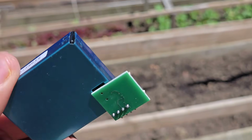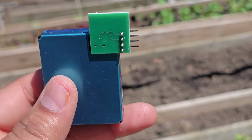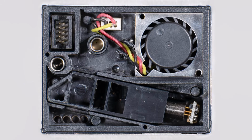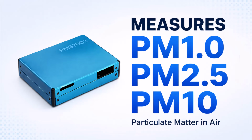Let's have an overview of the PMS7003 first. The PMS7003 is a digital particulate matter sensor used to measure dust particles present in the air. This sensor works on the principle of laser scattering. A small fan pulls air into the sensor, and a laser detects the particles passing through the air chamber. Based on the detected particles, the sensor calculates the particle concentration and sends the data through UART serial communication.